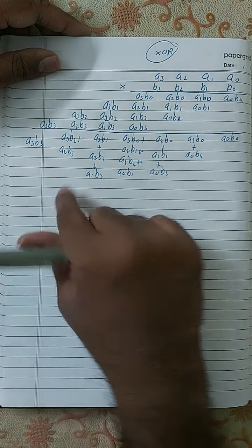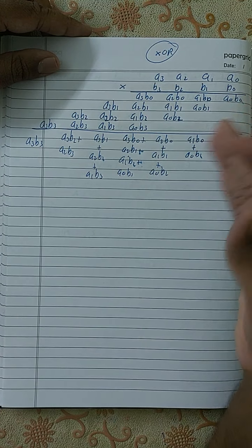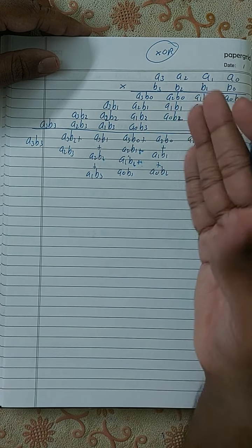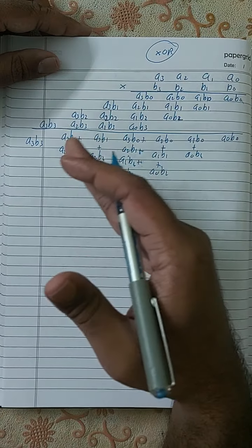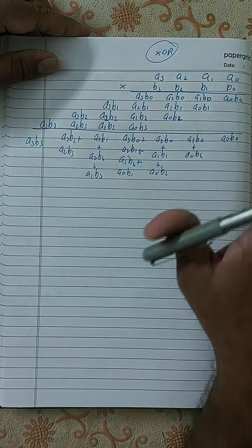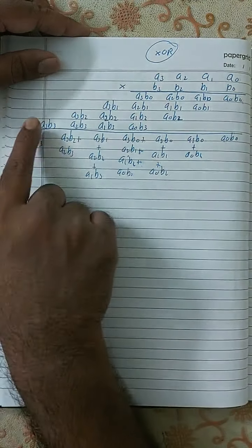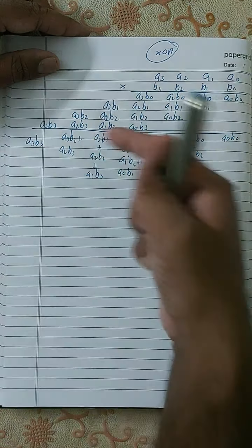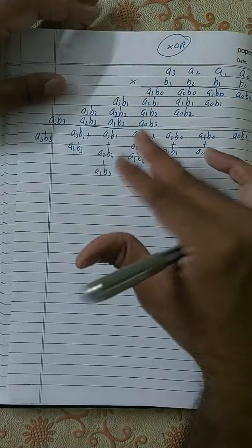Another interesting thing about this is there is no carry over here. You will never find a carry here, because like I told you, this is nothing but a pure XOR operation. There is no half adder or full adder operation here. Only XOR operation, which means there won't be any carry also. That means if you start adding from here or from here, both of them, you will get the same answer. That's another interesting aspect about this.